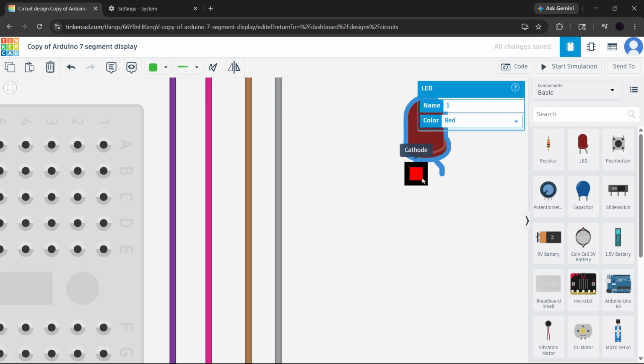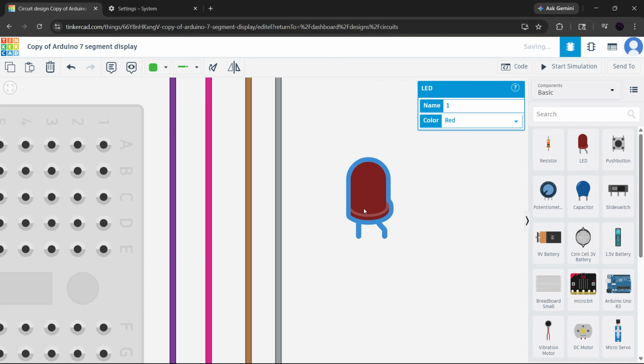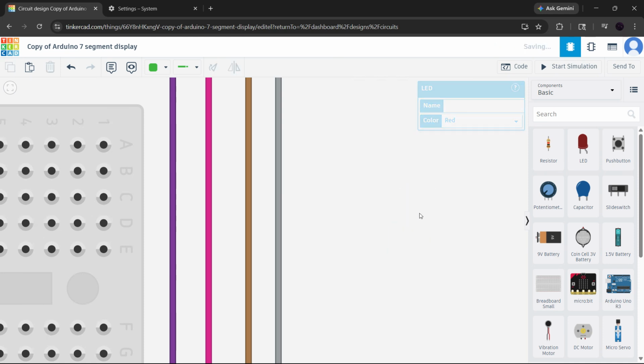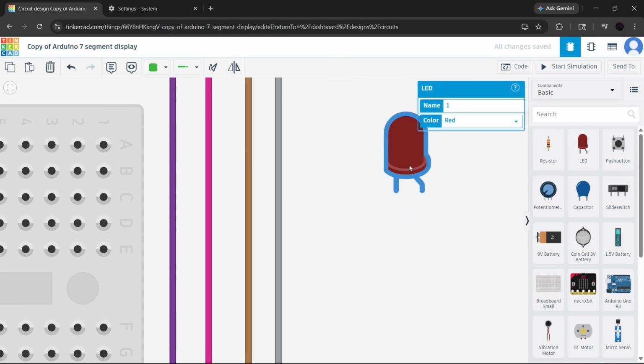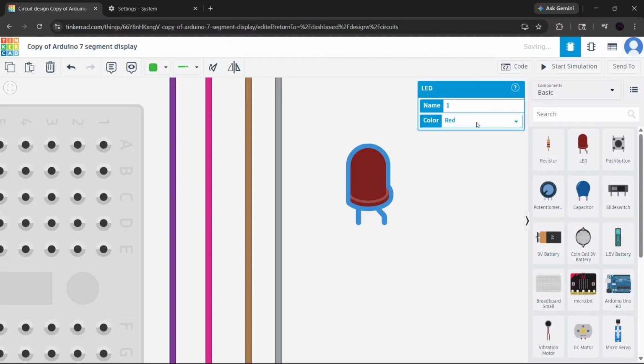If the LED is reversed, it will not light properly, and whenever you're using LEDs in Tinkercad, always use a 220 ohm resistor. That helps prevent the simulation from overloading or breaking the virtual bulb. This one small detail fixes a huge number of beginner circuit issues.